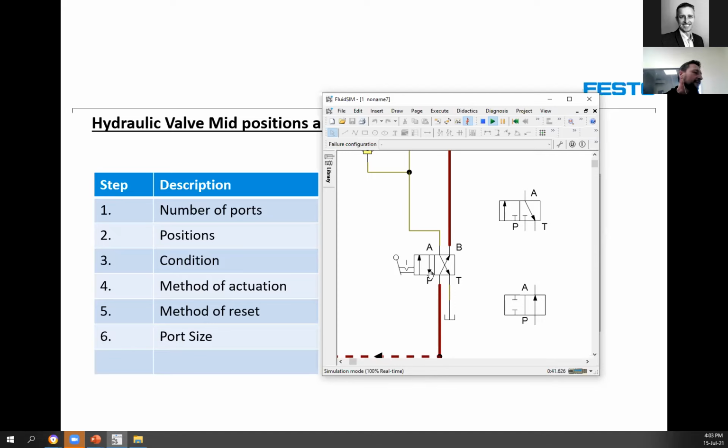This, in actual fact, is called a directional control valve, because you have two outlets, and you can choose where the oil should flow into and where the oil should flow out of. Okay, so what we're doing here is to change the direction of a cylinder.